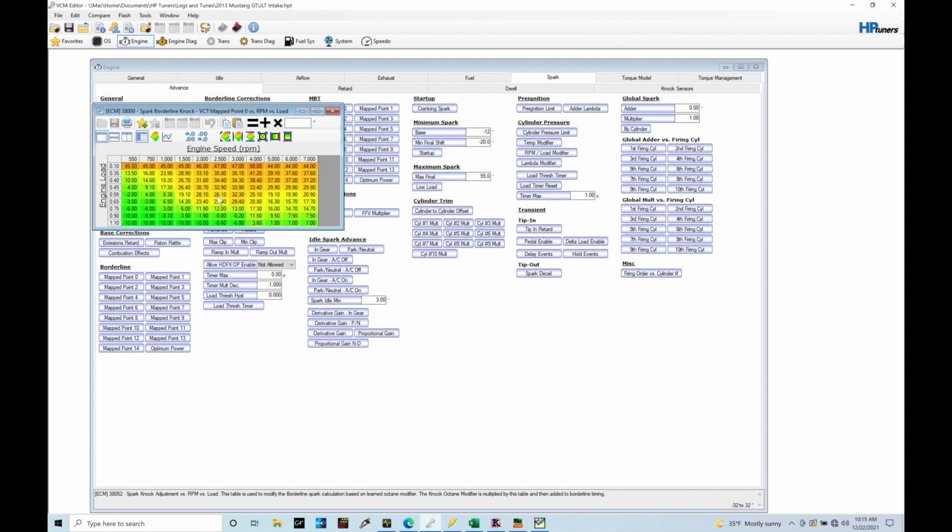Now, we're going to find that the piston's going to change direction. It's going to start to travel upwards on what's known as the compression stroke. That's where all the valves are shut, and we're compressing the fuel and air mixture. In that situation, the piston's traveling from that 180 degree marker, upwards towards the 360 degree marker, where it returns to top dead center. At that 360 degrees, that's going to be the point where we're between the compression stroke and the power stroke. That's where we initiate the spark, somewhere in that range.